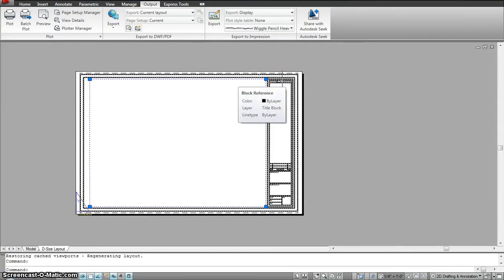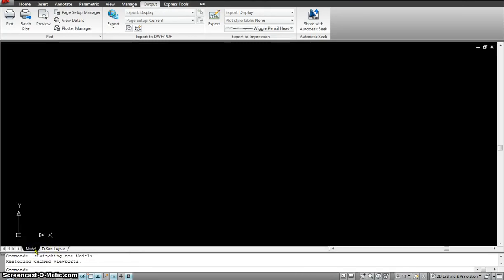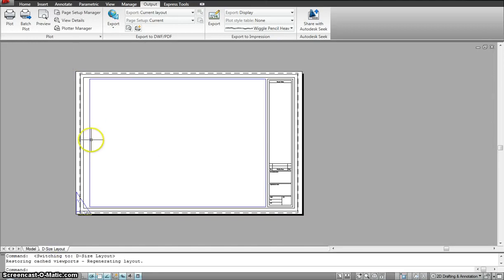Now every drawing that has to be printed needs to always have a title block, and the best place to put the title block is again in the layout space. In the model space, all you do is just draw. You can even dimension in the model space, provided you're using annotative dimension. Previously, when annotative dimension wasn't there, we always did the dimensions in the layout as well, and we left the model space just for drawing. But now you could use it for either.